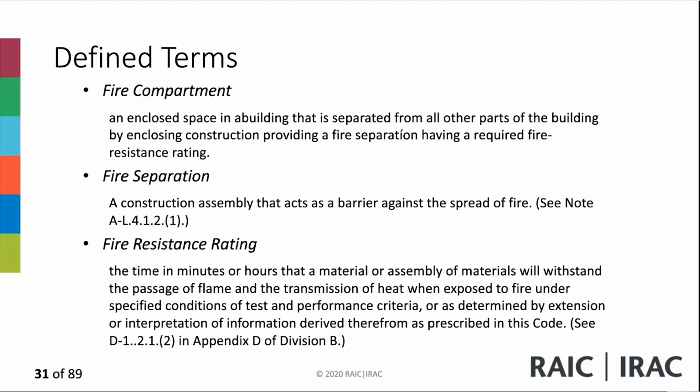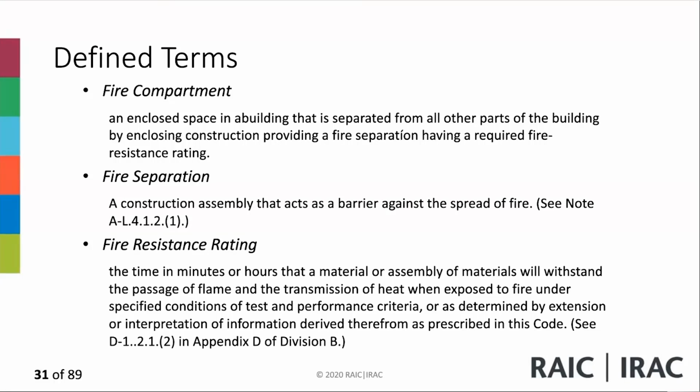I did my PCIN testing for complex buildings, and I tell you, it seems like everybody tests on Appendix D mostly. I'm not an architect, so I wouldn't know what's in there exactly, but definitely in terms of estimating the fire resistance rating of assemblies when you're using the code, Appendix D seems to be an excellent reference for that.